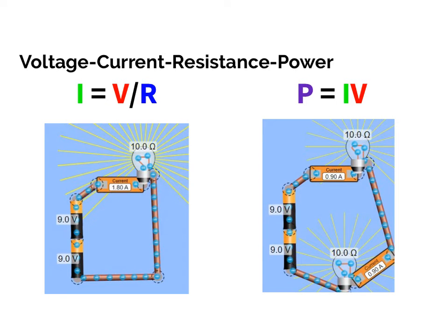All right, so the idea is if we connect these variables, we talked about voltage, current, resistance, and now power. Voltage, again, is the energy being supplied by the batteries. So say I have here 2 batteries, each having 9 volts. I know that in total there's going to be 18 volts supplied to the circuit. That voltage is going to produce a current. Now the current, 1.8 amps, is also based upon the resistance within the circuit, which we see as 10 ohms. So there's a relationship between the voltage, current, and resistance, and that's this Ohm's law we talked about in our previous section.